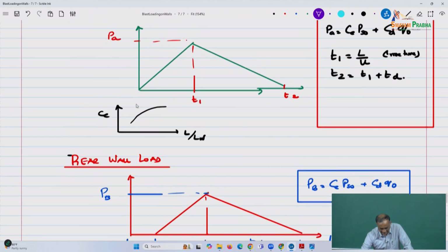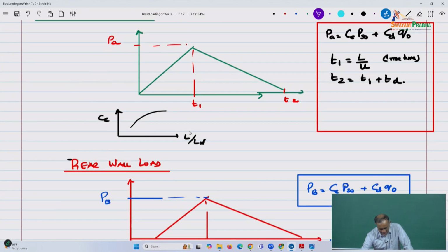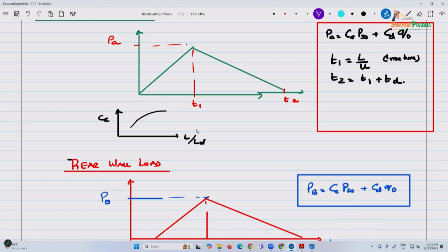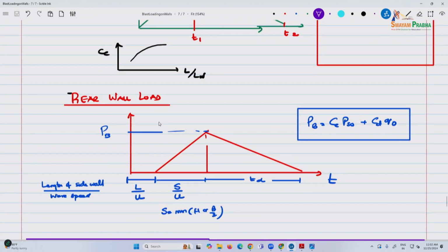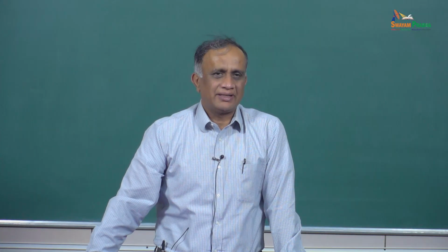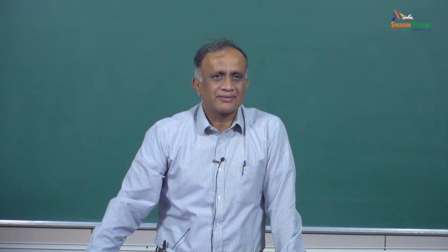So in the graph that you see here, your CE values, if your L is much larger, I think it's LW by L maybe, I might have reversed length and wavelength, that factor comes from here. But by definition we say that blast effects are ignored, so you can justify in your design saying that it is beyond that, so you're ignoring it.